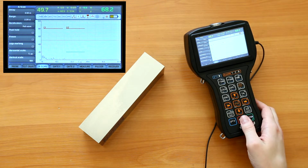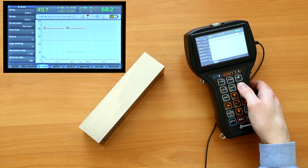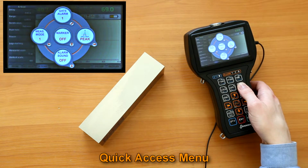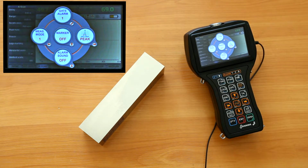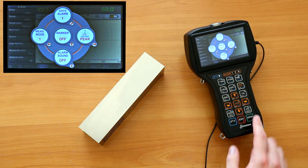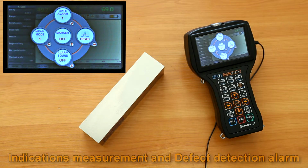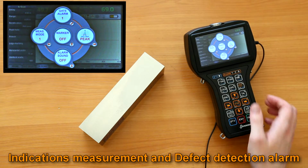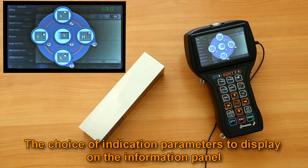The Quick Access menu button brings up and cycles 3 pages of the Quick Access menu. At each page there is a cross of 5 items, which are driven with the corresponding cross of buttons. The first page of this menu is dedicated to the indications, measurement and defect detection alarm. The second to the choice of indication parameters to display on the information panel.